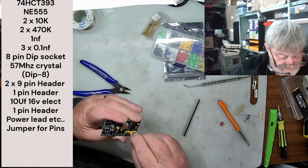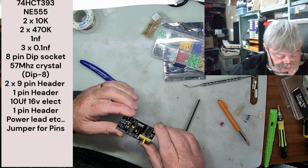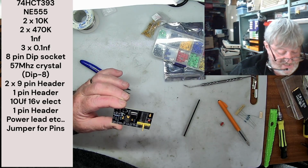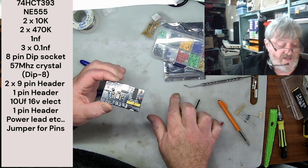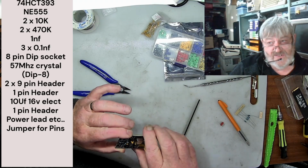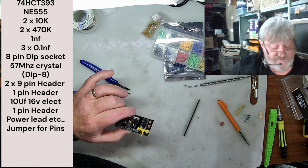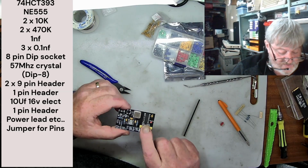But the one I want is I've marked it in the middle there, which is divided by 16. And what that one gives me is 3.56 megahertz, and that's very close to where I need to be for the CPU, and I think it's 3.567, something like that. So it's within a few hertz difference, so that should cause it to run fine. So that's where I need to be.